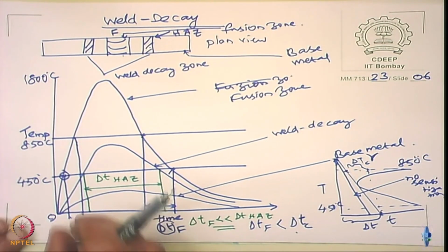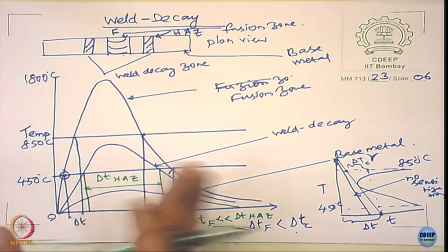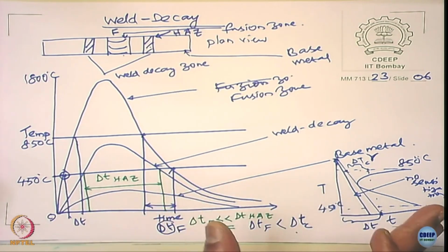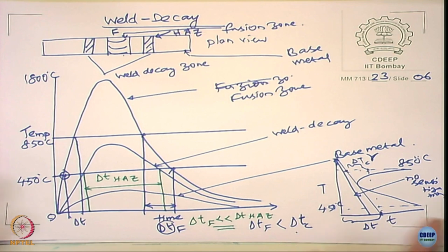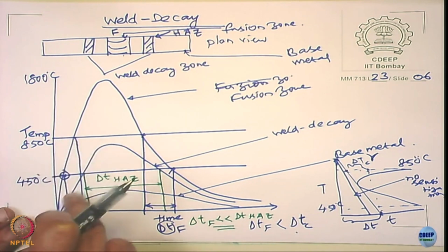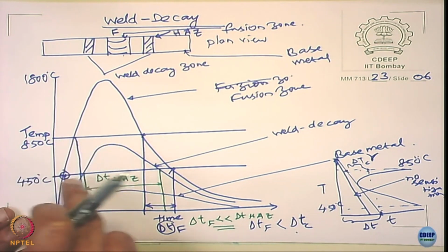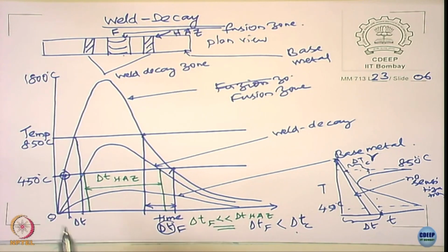So that means this one anyway has no significance from the point of view of welding, right, there is no significance. I am only trying to analyze the thermal cycles during a welding process, okay, but otherwise this one does not have any significance at all, because even it gets sensitized, for argument's sake, they get dissolved when the temperature exceeds the solubility of the chromium carbide precipitate.